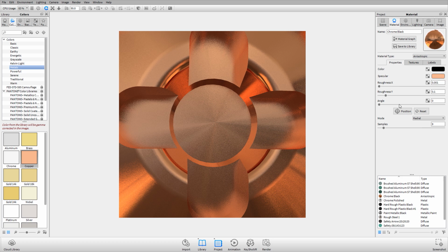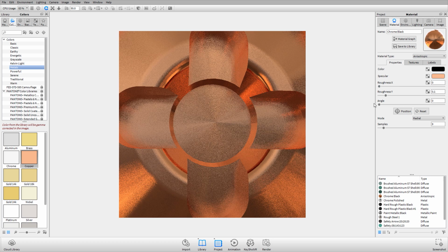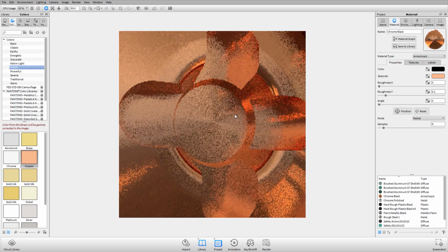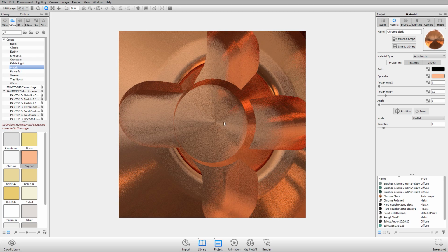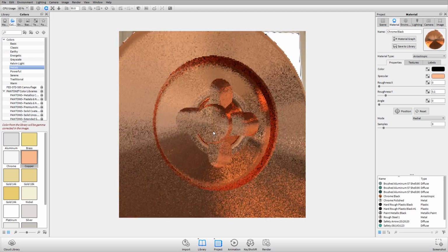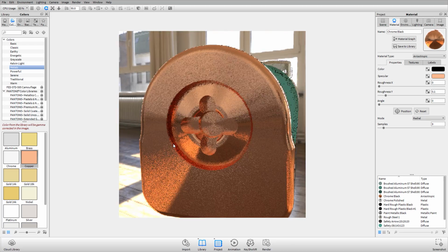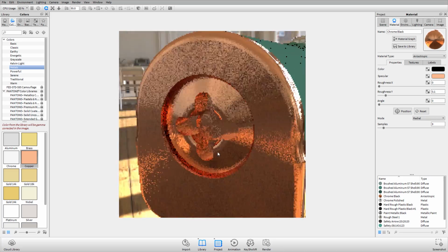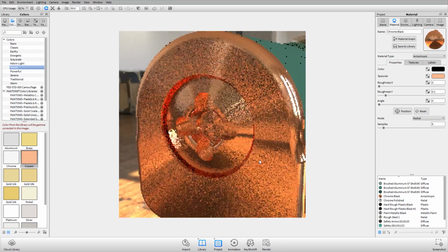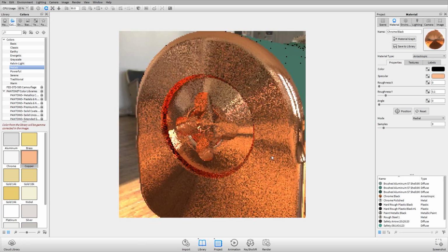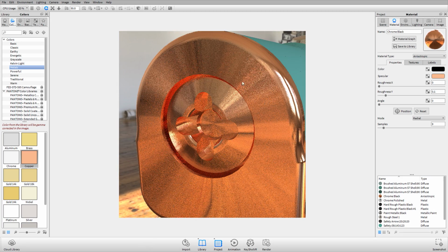And with the radial, I don't tend to have roughness in both. I'll just have it in one direction. So now roughness X of 0, roughness Y of 0.1. Now I'm seeing those really sharp kind of radial reflections. And if I rotate the environment around, I'm doing that by holding control and clicking and dragging my real-time view, you can see that I'm getting that really nice, bright kind of burst pattern.